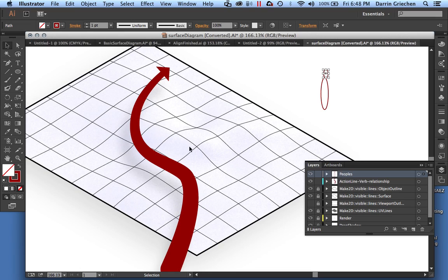And I'm going to select both of them, and I want them to be filled. So I swap those two. So now it's filled. I'm going to take that head and just use the cursor keys to move down slightly so that it's touching. And you could make a couple of these guys, but right now what I'm going to do is select both of them by just clicking and dragging a box to select them. And then I'm going to group them so I can keep them together.